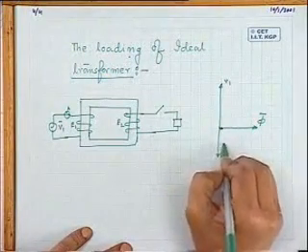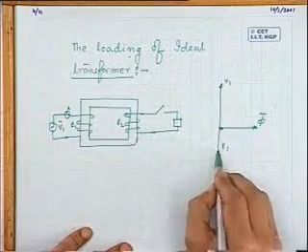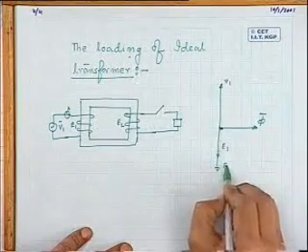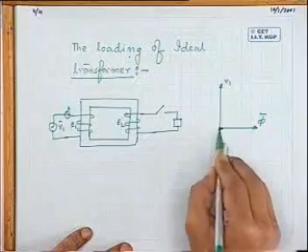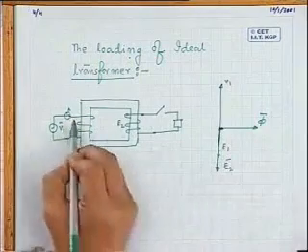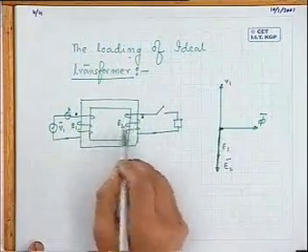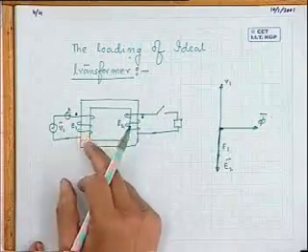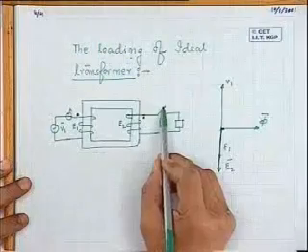So some current was there, like this. And in the secondary, I have got both E1 here, and suppose it is a step up or step down transformer; depending upon that, this E2 will be decided. I think that is clear to you. This E2 is there. Obviously, the dot is known to me either by going through the sense of the winding or by doing some test. These dots are known.